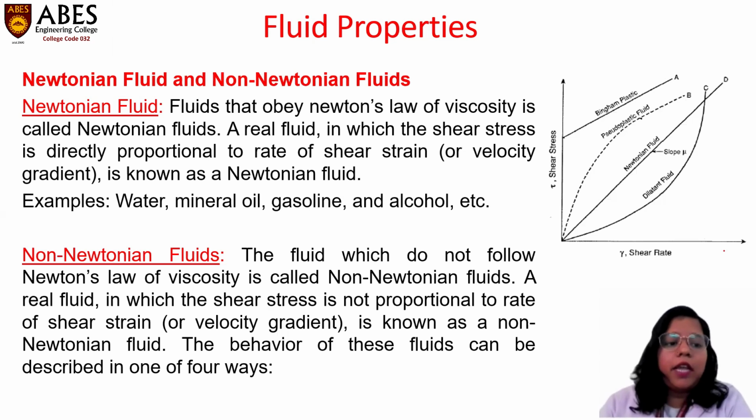And the next is non-Newtonian fluid. What are non-Newtonian fluids? These are fluids which do not follow Newton's law of viscosity. A real fluid in which the shear stress is not proportional to the rate of shear strain, or not proportional to the velocity gradient, is termed a non-Newtonian fluid.